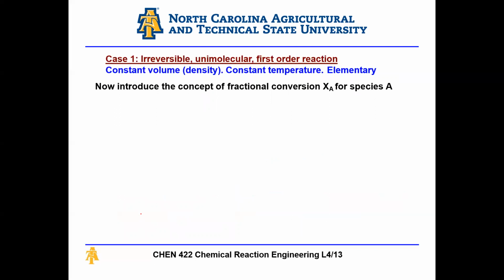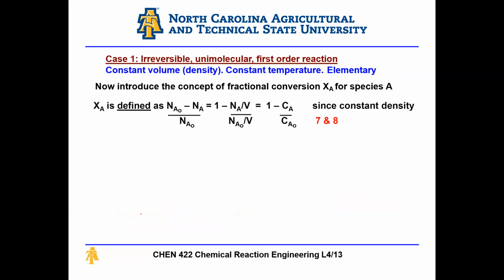We also introduced the concept of conversion, so you should understand what conversion is and be able to use it when solving problems. And again, X_A has different forms: X_A = 1 - C_A/C_A0, or X_A = (C_A0 - C_A)/C_A0.